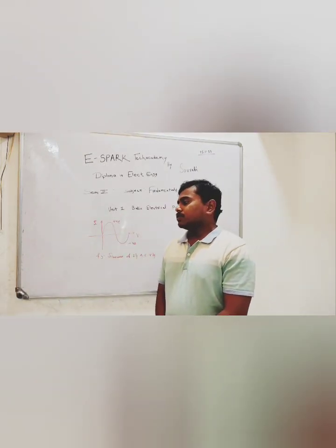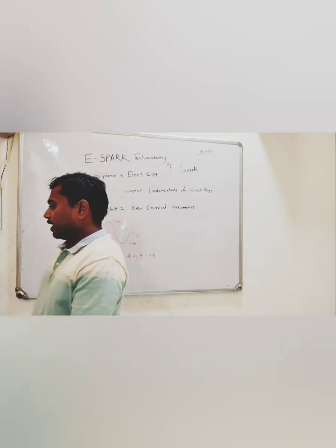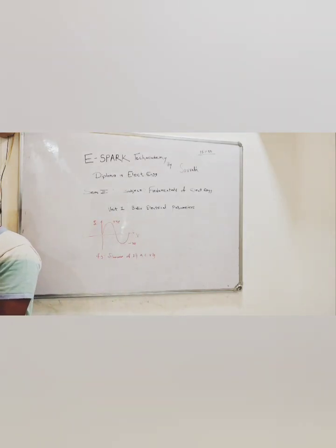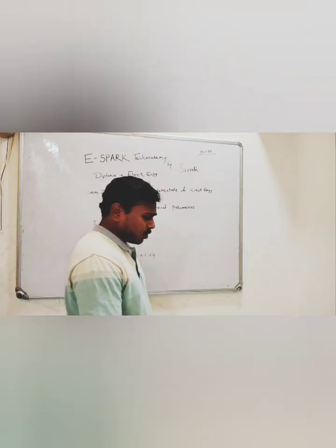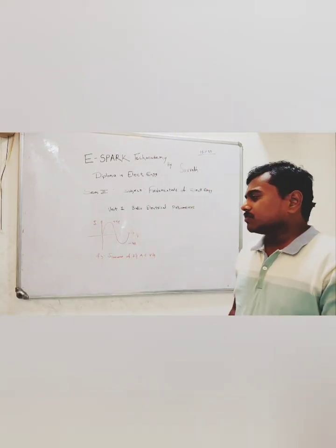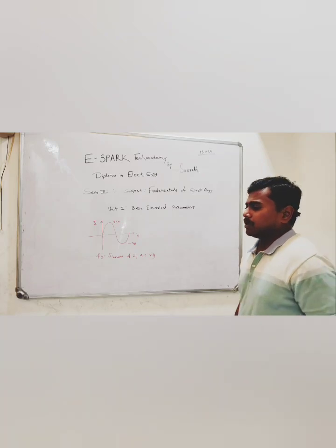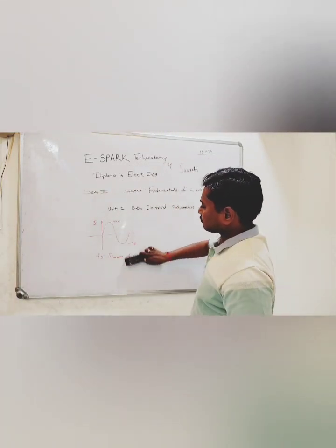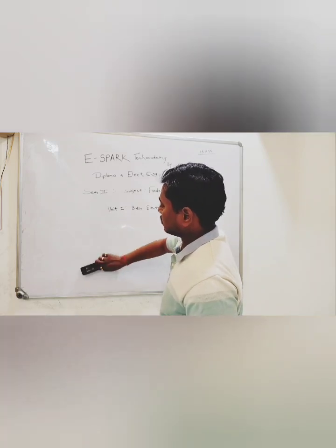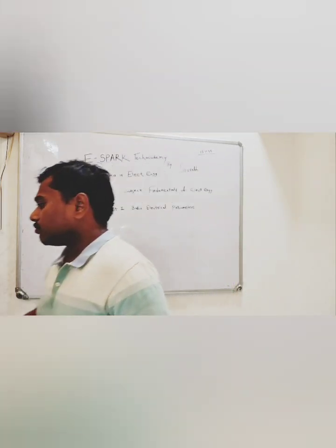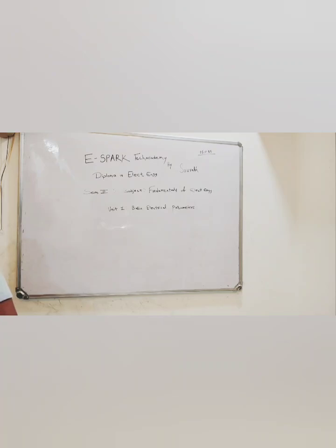The ideal voltage source has internal resistance of zero. The voltage always remains constant even if you increase your load. Practically this is not possible, because an ideal system does not exist in practice. Still we will be studying this.